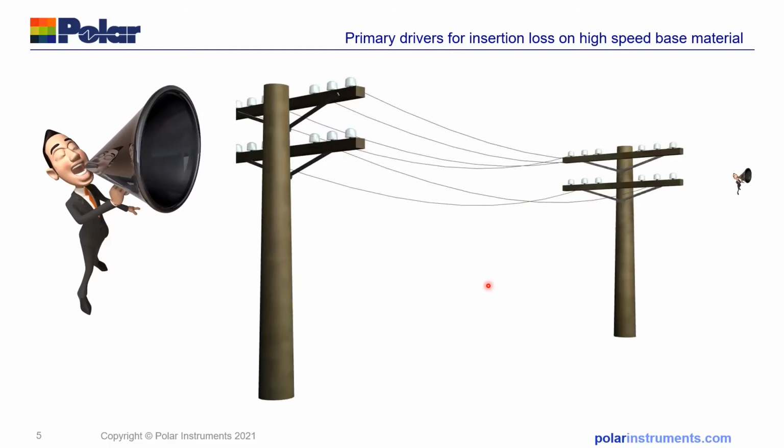But what causes those losses? And you've heard Manfred talk about the losses in the base material, and Julie about the losses on the copper. What we're going to do is break those down and show you how to estimate and model how much loss comes from the copper and how much loss comes from the dielectric.